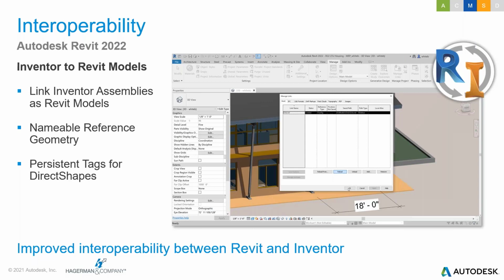You can link Revit models exported from Inventor. Inventor incorporates the new Simplify command to produce an RVT model containing only the components and features needed for the Revit design. The Revit export and Simplify command have been combined in Inventor and added to the property panel for a complete set of options in one easy-to-use interface. You can link the resulting RVT files into Revit projects.